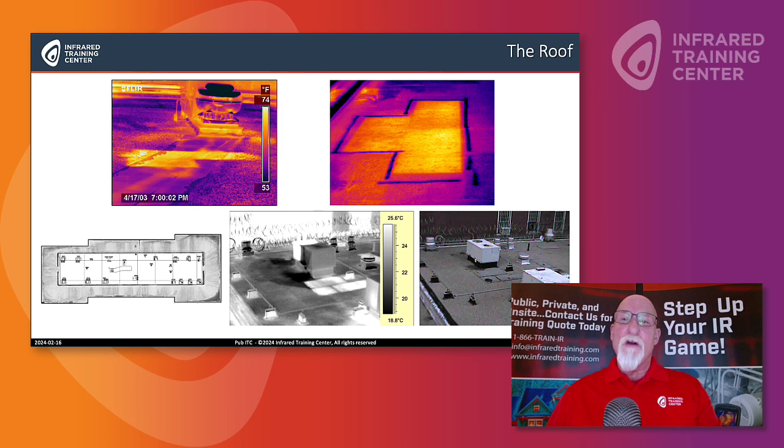Secondly, because of safety, I don't want to be walking off the roof into the parking lot or off one roof to another. I always recommend that you have somebody on the roof with you. That person can use the chalk or whatever marking medium you're going to use. I just use the laser pointer on my camera and detail where to mark, so that the repair person coming up to repair that section of the roof can core it, make sure that the substrate is not ruined underneath or oversaturated, and then do a nice seal, whether they weld a new piece in or apply some asphalt to the roof.